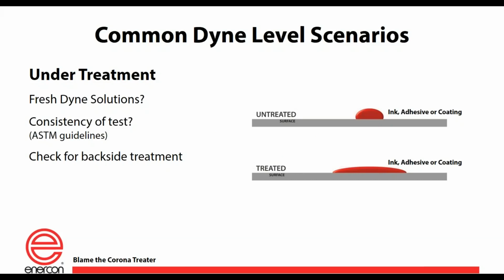I always forget about this side of things because I make assumptions that everybody just uses fresh Dyne solution. Some of you out there have asked me this question when I visited with you. You'll say, well, how long are pens good for? Or where should I keep these bottles of Dyne solution? Or when should I change the bottles of Dyne solution is a really common question. The answer to that is, generally speaking, in bottles of Dyne solution, generally people like to turn them over in 6 months' time, and that's assuming the solution is kept in a cabinet. It's not just left out in the open.